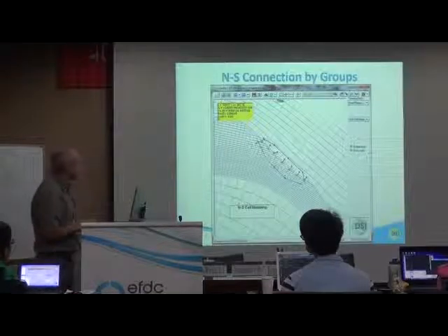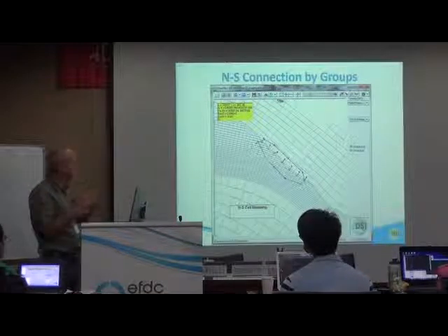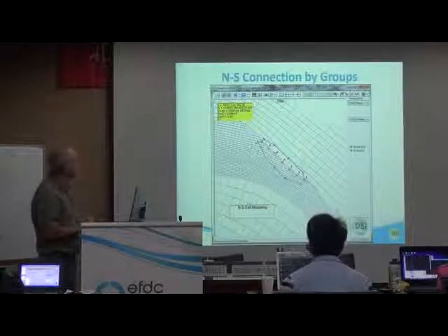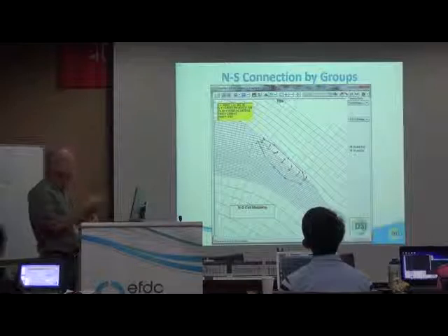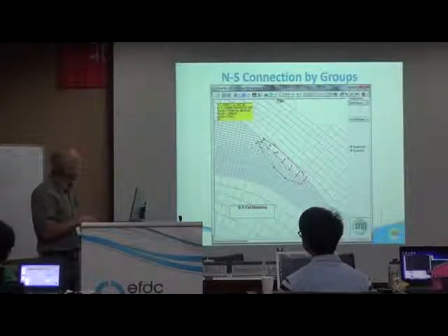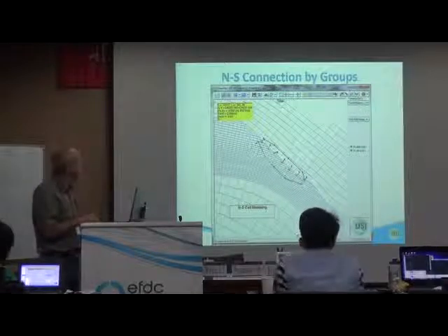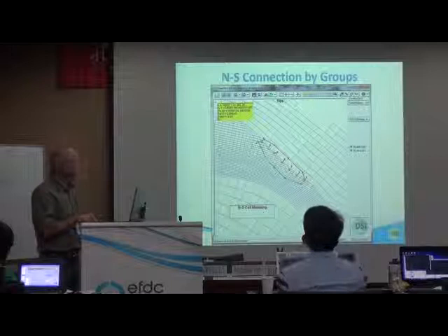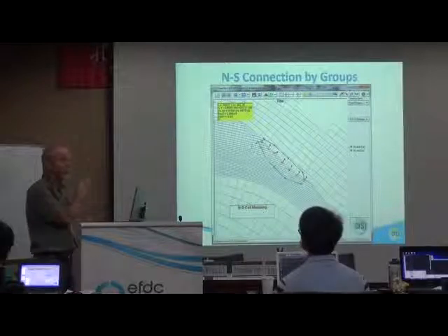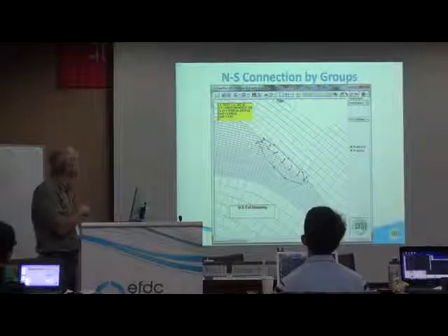If you're doing a lot of connections of grids, subgrids, if you have subdomains and you're connecting one subdomain to another, this tool here is real nice where you can just select or build a polygon that will automatically connect two subgrids together based on the best matches on their faces, north to south. So that's a real huge time saver if you've got big grids.